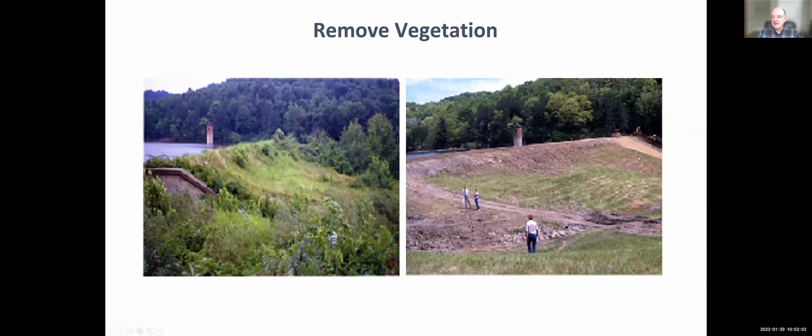Of course, you can get a sense in this far corner where these larger trees were. They were taking out root balls, and there's a strategy for doing that. And then they have to reconstruct the dam at that location. It's not simply chopping down the vegetation. So it's a lot more effort involved, and you're probably needing permission to do that from your dam safety officer.